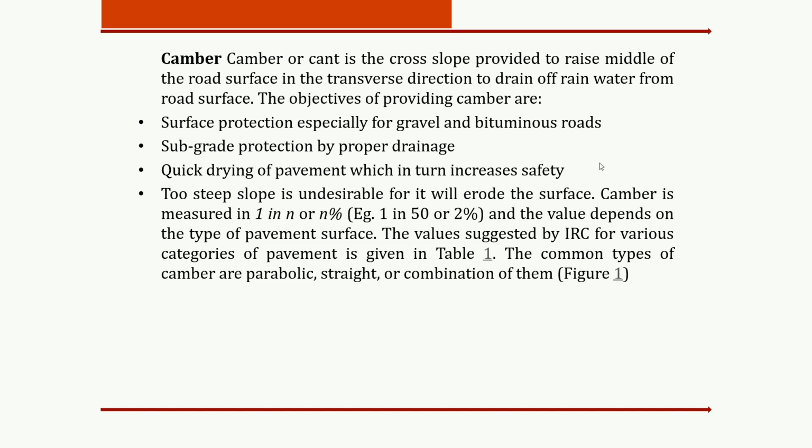So these cambers are available in various slopes, and we are providing this camber as per the recommendation given by the IRC, that is Indian Road Congress. It has various types of slope like 1 is to 10, 1 is to 50, and as per the requirement of topography and the requirement of this site, we are changing the size and slope of the camber, and we are providing that. So I hope you can understand the concept of the camber.